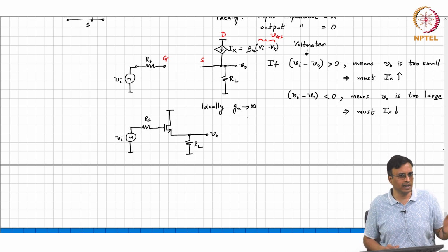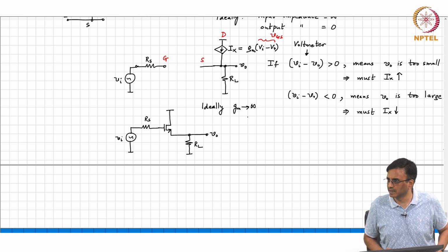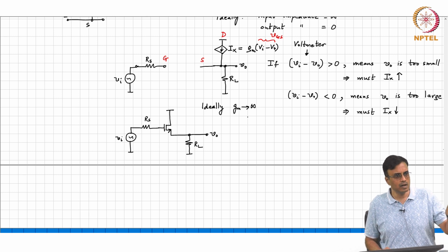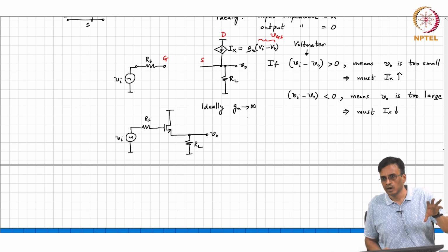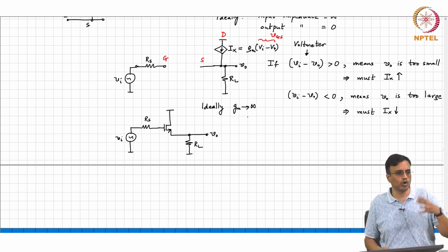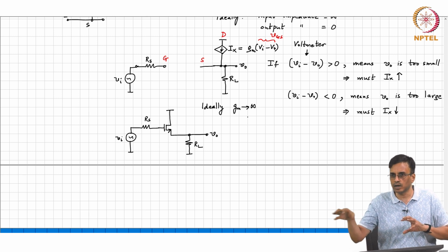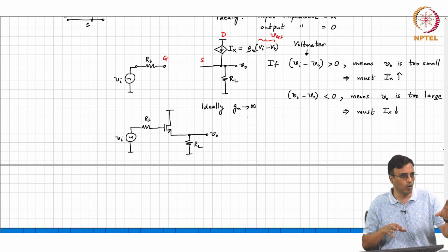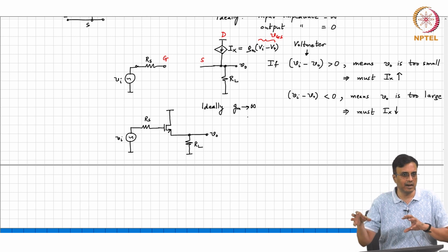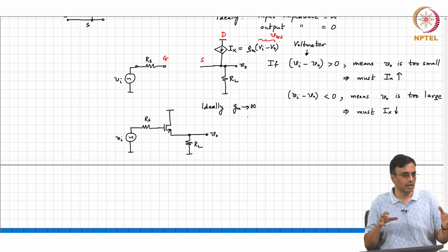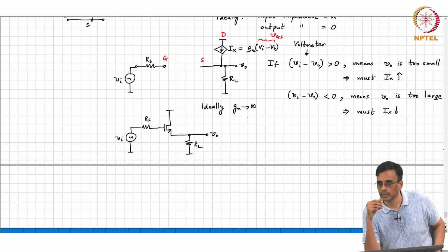You already know at least 5 or 6 ways of biasing the transistor. You can pick your favorite way. Once you bias the transistor, you also know how to get rid of elements that you do not want, and keep elements that you want, by adding infinite inductors and infinite capacitors, correct? And then you must make sure that your incremental circuit looks like this one.